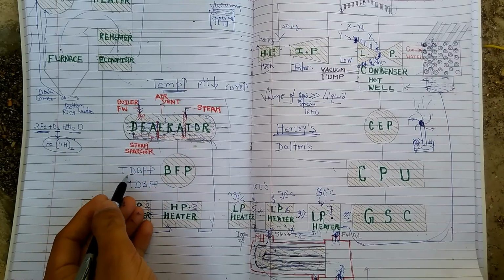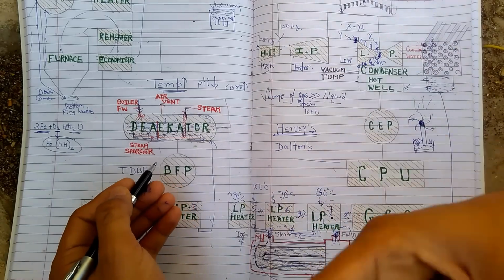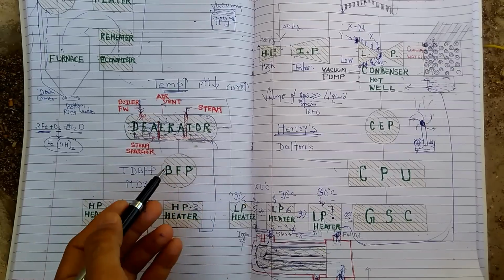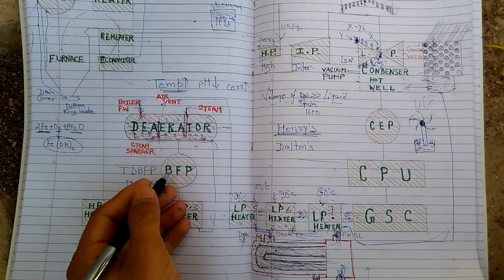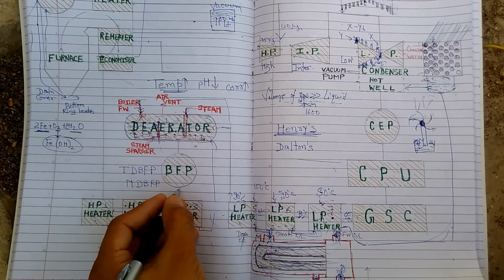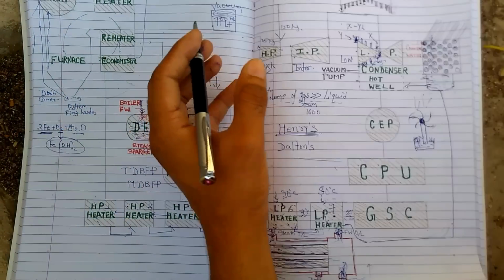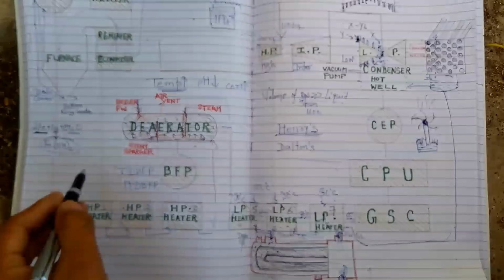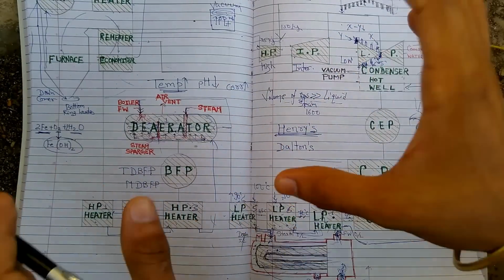To reduce the auxiliary consumption, what we do is we put a turbine on this pump, and that turbine is rotated by steam. The steam may be tapped from some stage of the turbine, and it rotates the turbine, and that makes the pump work. Okay, now the BFP has to be very powerful to create that much pressure, so that my feed water gets from here to here and circulates into the boiler, and after that also goes to the HP turbine and does work on it. I mean from here to here to here to here, for the complete cycle up to here, up to CEP, you need to create very high pressure.